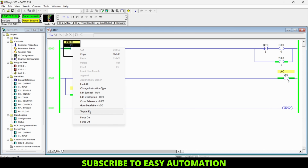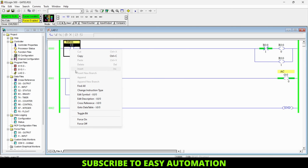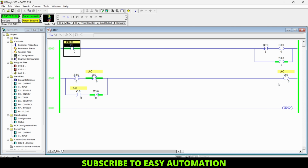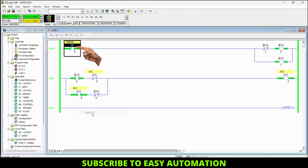I have turned on the output, so our output is on now, and if I toggle this bit high, then our output will go off. The condition happening here is that whenever I toggle this bit high while our output is on, the trigger pulse is generated here, and the trigger pulse will come to this NO contact, and this NO contact will become NC.